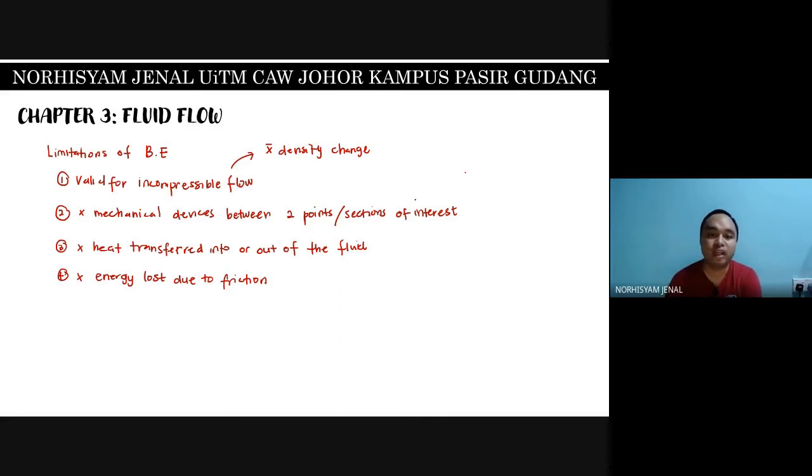And usually we will add multiple mechanical devices to help the fluid to flow. For example, we're adding up pumps, and some parts of the mechanical device, for example, a turbine. Because of these 3 things that are happening, we might have a density change also in the system. So in reality, these limitations will never all hold. It means that every single one of them can be violated in reality. So the Bernoulli equation is something that we study with the idea of no losses or no other things happening from 1 to 4 in the system, and it is easy for us to do calculation.